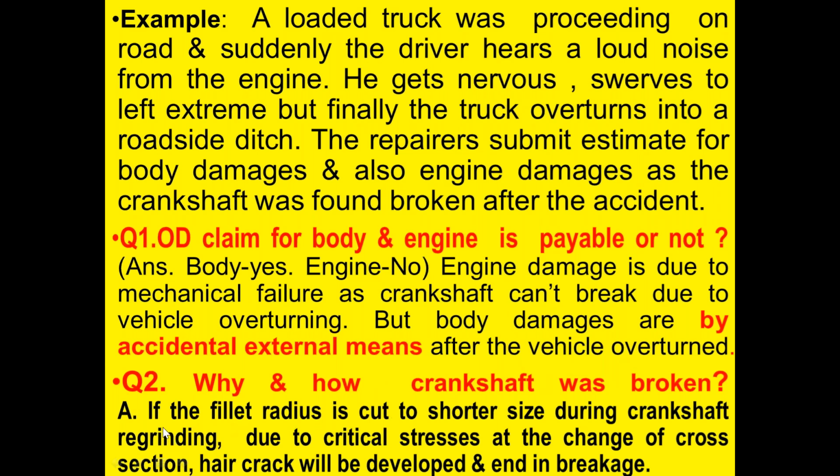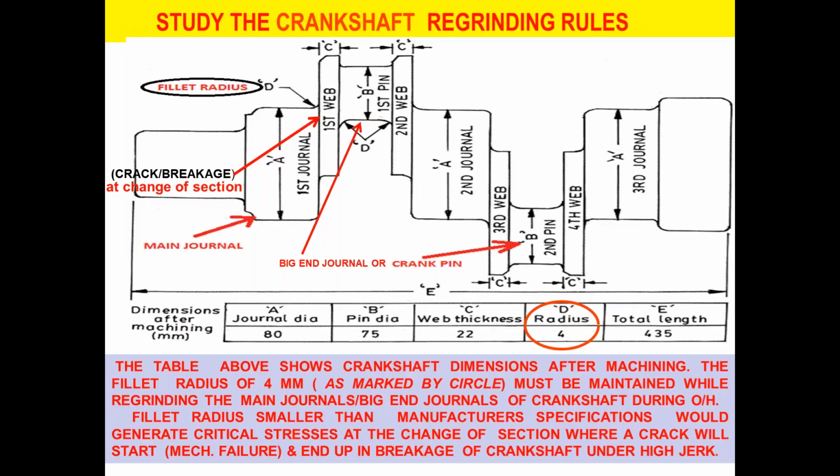Question 2. Why and how was the crankshaft broken? If the fillet radius is cut to a shorter size during crankshaft regrinding, then due to critical stresses at the change of cross section, a crack will be developed here and end in the breakage of the crankshaft. You should study the crankshaft regrinding rules.